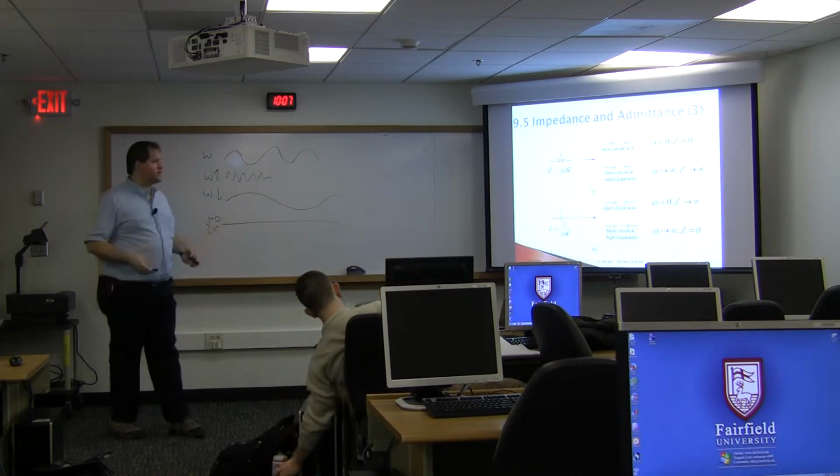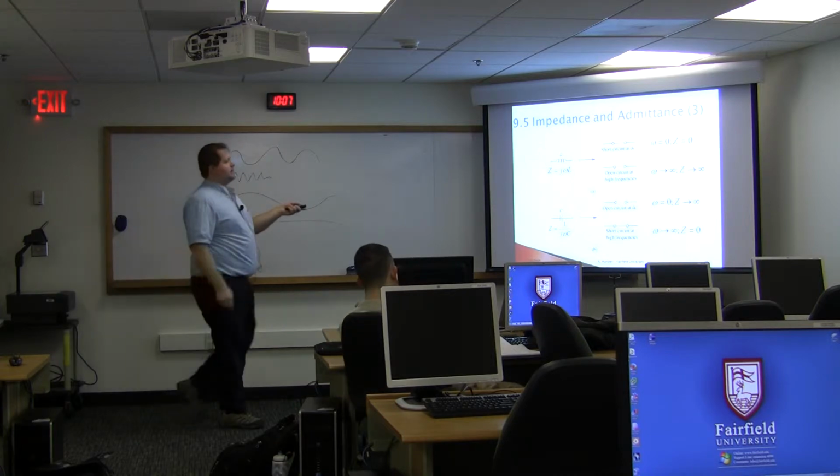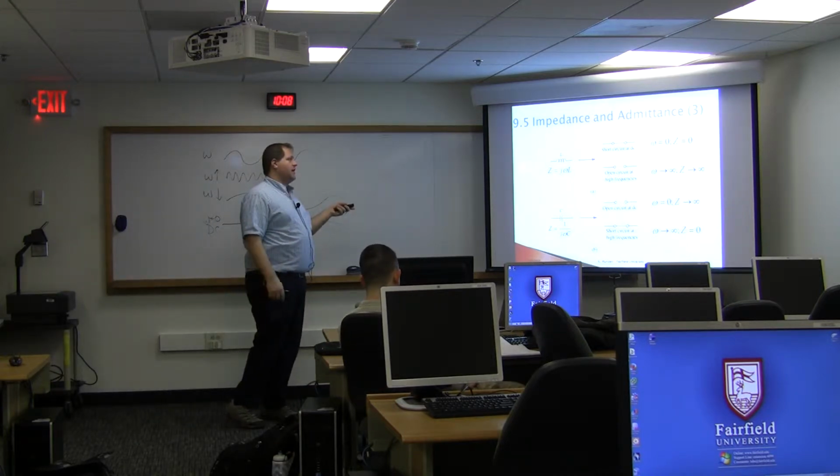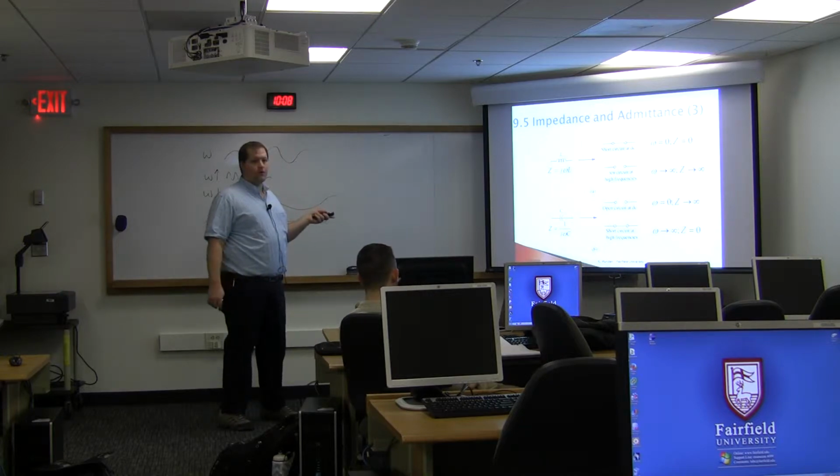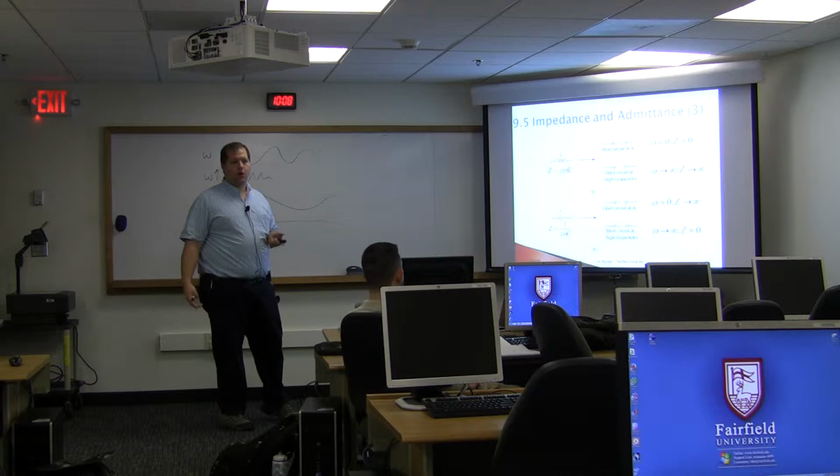So if I were to look at a circuit, as we start thinking about filters, and I say, well, here's an inductor, what is that going to let go through? Well, it looks like a short circuit to DC. So low frequencies can go through an inductor. But high frequencies, this looks like an open circuit, so high frequencies can't go through.